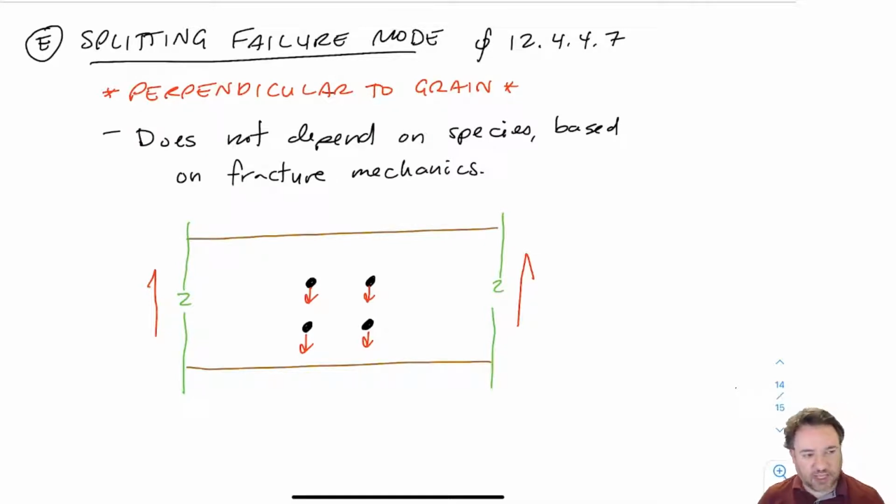So here we have a piece of wood. Now we're looking at it on its side, and we have bolts inside this piece of wood. Now instead of the bolt wanting to tear out the side, or have group tear out, or net tension, or even bolt yielding, we're looking at what happens if the bolt wants to move perpendicular to grain. So I'm pulling down, which means that basically I'm grabbing this wood and pulling it down from a certain height.